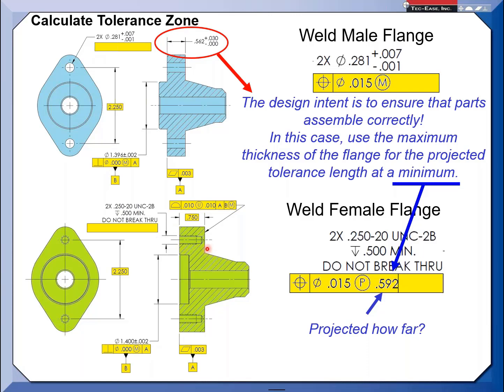Now the standard, if you're dealing with the MBD world, let's say you don't have a drawing, then with the MBD, what you've got to do is have the leader line touch the circle on the surface of the side you're projecting out. So the 41 has a little bit different rules than 14.5. Okay. Just FYI.